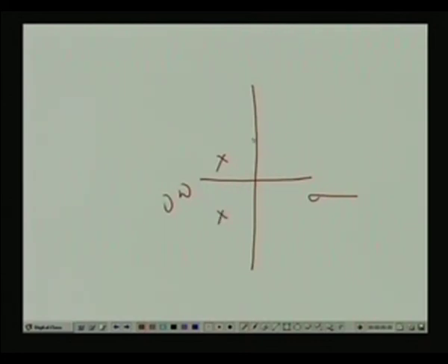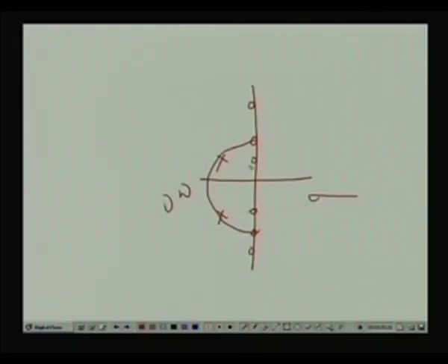That means in the case of notch circuits, as you know, if you look at this sigma j omega plane, we have complex conjugate poles, and either I can have a 0 here, or here, or here. Now if it does not cancel, that means there is no real part of the zeros. That is only possible if the coefficient of S in the numerator is 0, otherwise there will be no real part. Now what will happen if the real part remains, if due to signal subtraction it is not complete? You will find that it will remain. So this will be shifted a little bit to this side, so that will create the problem.